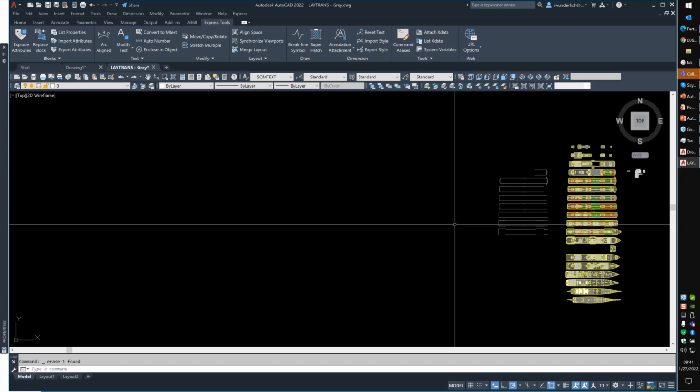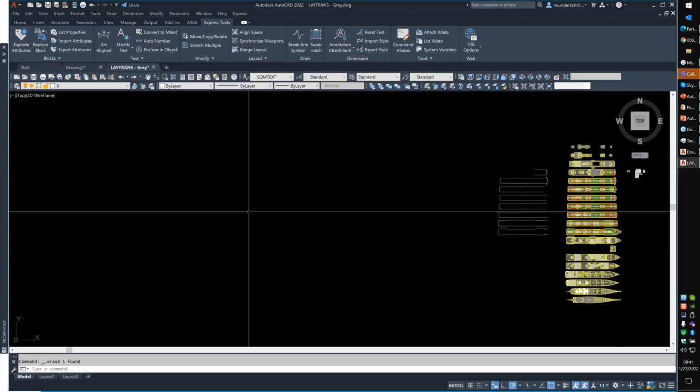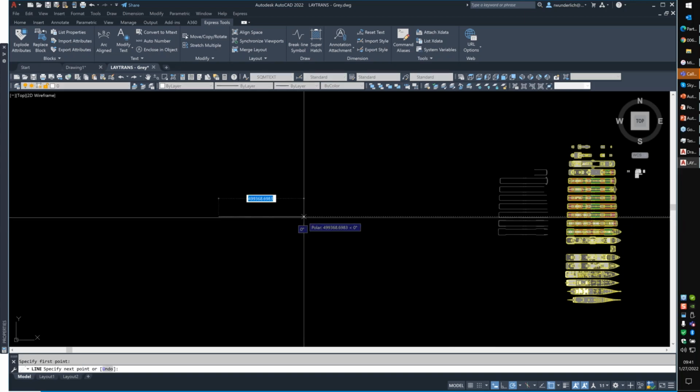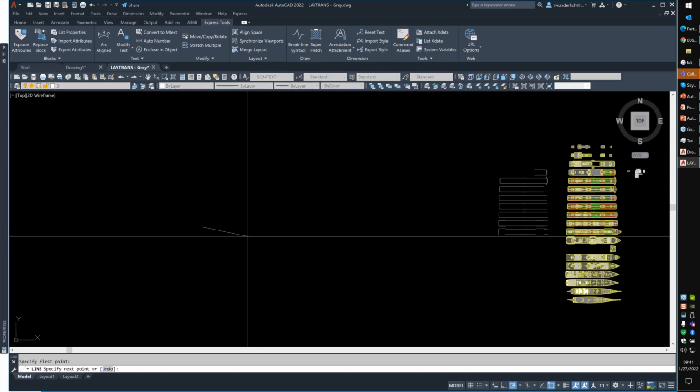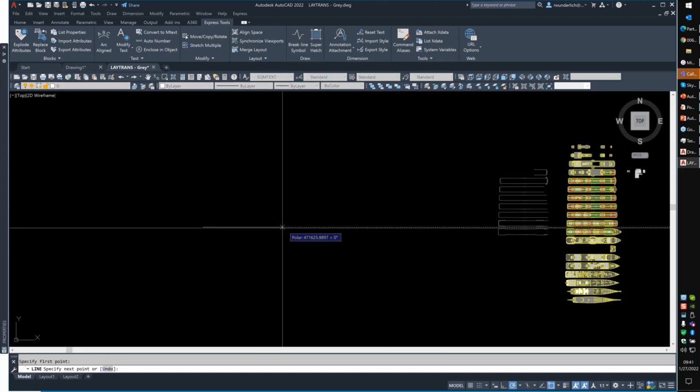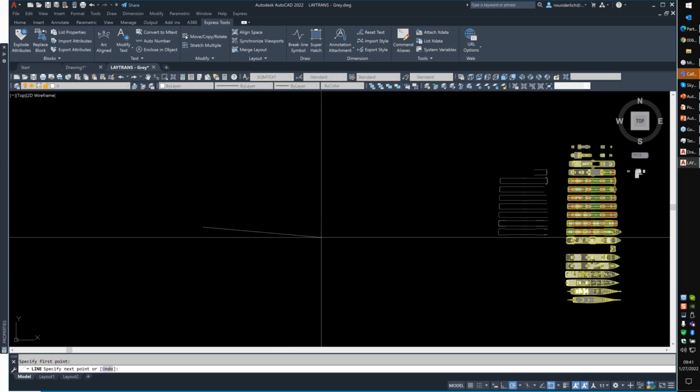But you can find that you can draft things a lot faster if you're doing basic drafting with dynamic input on, because now you have a visual cue as to where you're going. So again, I can draw a line, type in a specific length here and then tab for a specific angle. Whereas if I turn it off, now I can go in the direction I want and type in the value and hit enter and it'll get there, but it doesn't matter where I'm at.